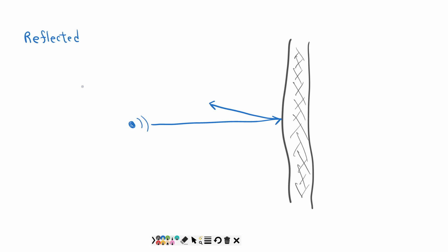We're actually going to spend one video just looking at this, the reflection part. What else can happen? Well, some of that sound energy can come into here and essentially shake around whatever it is that's inside this wall, the mechanics of this wall. Essentially what's going to happen here on a microscopic level is that energy, remember, energy has to be conserved, it just doesn't disappear. That energy gets turned into heat. It's absorbed in the structure itself.